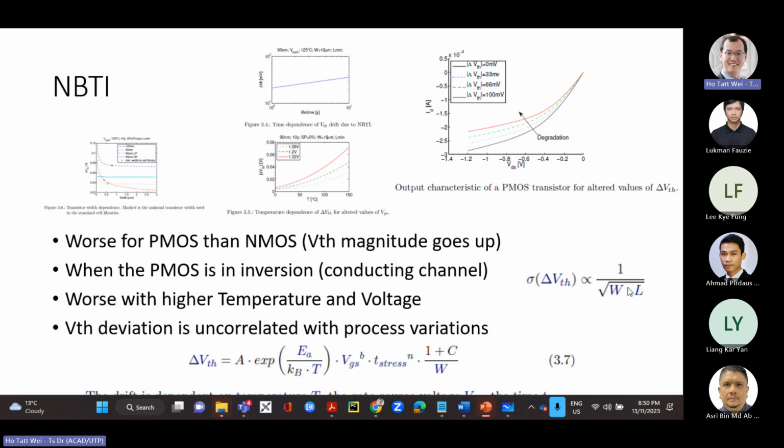So these equations are nice because they actually tell you how to compare logic gates in a digital path. And you can use this as a rule of thumb to say this gate is going to age worse than this gate, which is going to age worse than this gate, and this particular transistor is going to be the worst case, and all that.